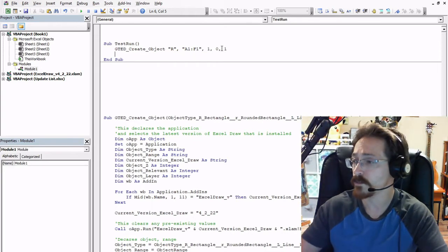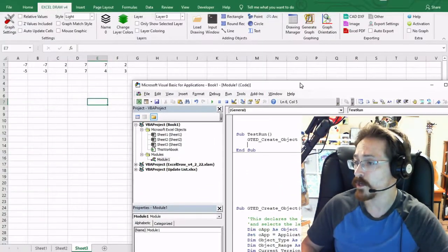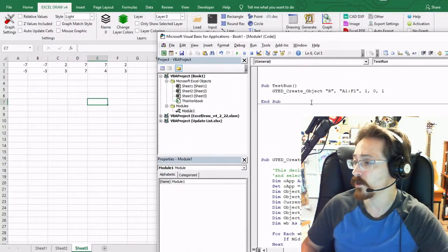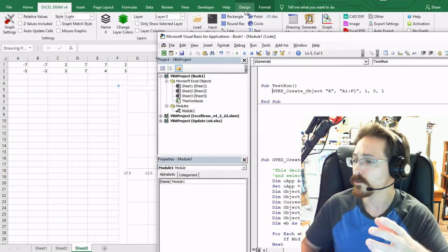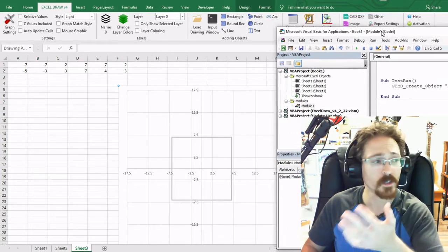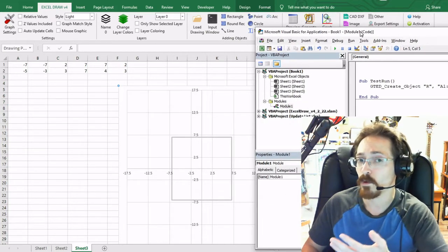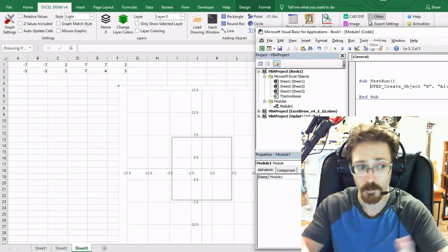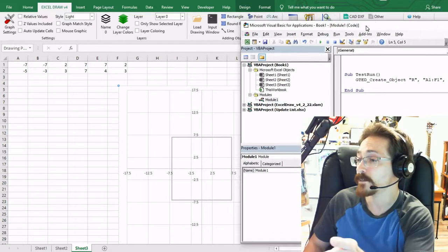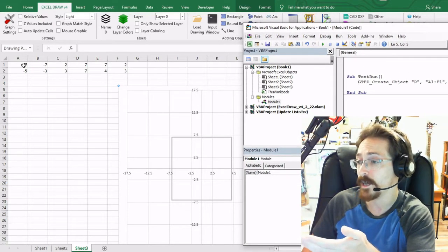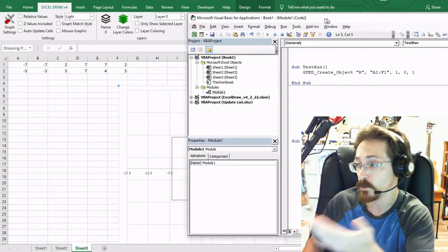And if I run this, it's going to create a rectangle with the first line of code. So I'm going to go ahead and hit play with this. And it's going to take a little bit because I am doing a recording. So, you know, this took about a second. Normally it won't take that long; because I am recording, it uses up some processing power. But yes, as you can see, we have created a box using VBA code.